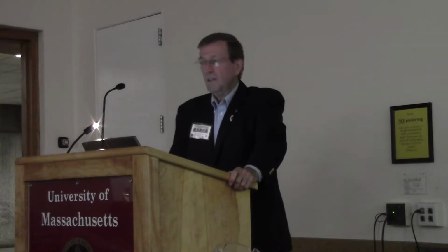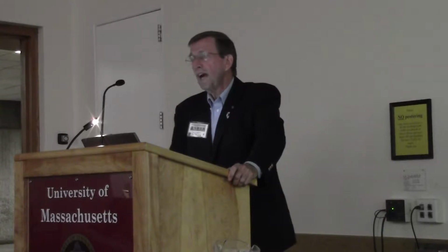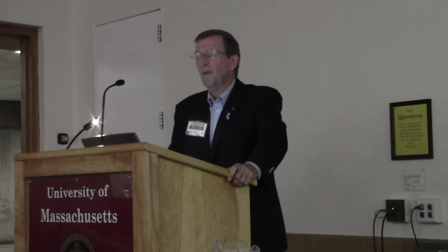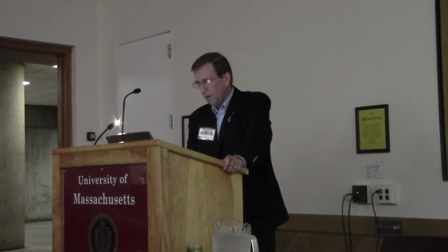Gasifiers, especially the TLUDs, are air-controlled stoves, air-controlled devices. When you're looking at other types of cook stoves, they are fuel-controlled. Two sticks in is twice the fire of one stick in, and then put in four sticks if you want a bigger fire still. Here we shut down the air, we bring on more air, and you can almost make these things stand up and walk and talk for you by controlling the air. Air for primary, which is going to give you how much gases are being produced, and air for secondary, which is going to control the combustion of what's coming off of those gases.